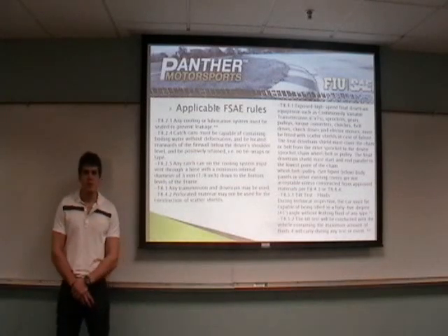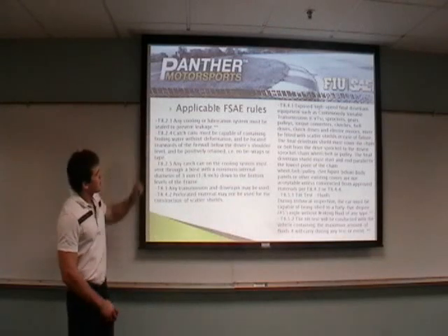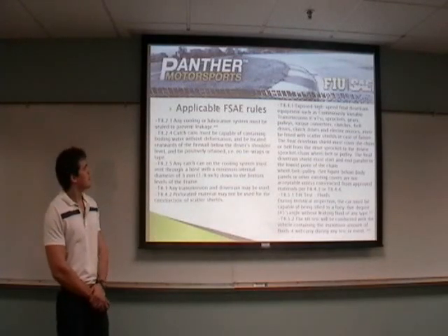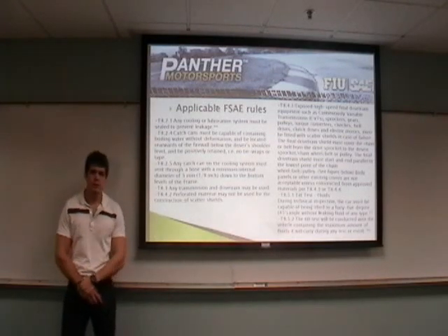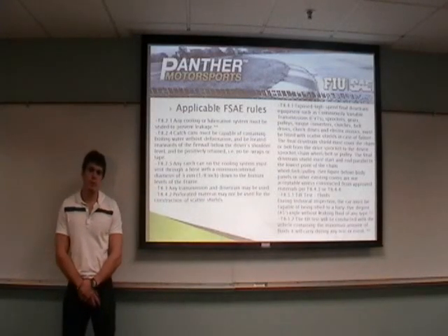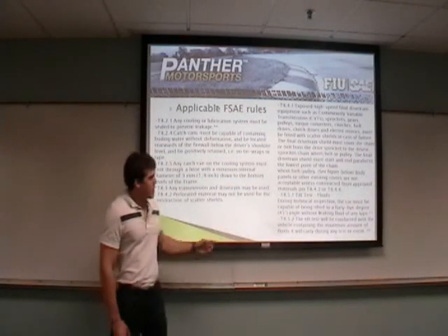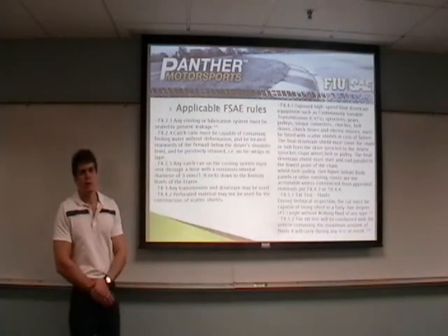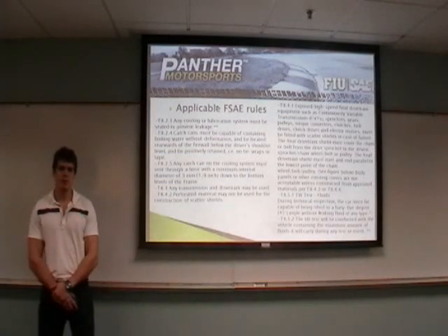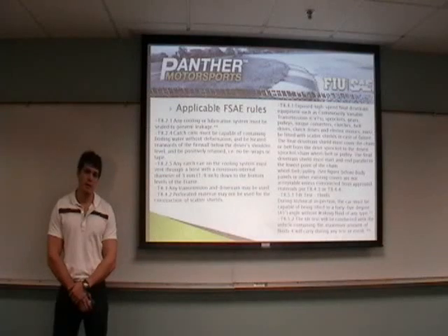These are the applicable FSAE rules to the differential. I'd like to highlight a couple. Right here, any cooling or lubrication system must be sealed to prevent leakage. During last season, the differential was leaking, which renders the car disqualified. They can't compete. And it also must go through the tilt test, in which the car will be tilted at 45 degrees, and the reservoir will have to be full, and it cannot leak anything.